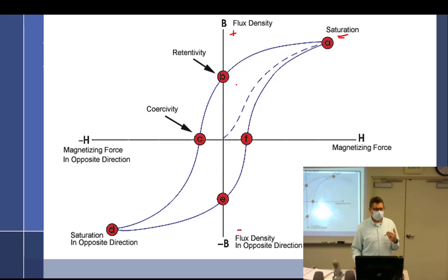And again, it's kind of cool because a lot of you have already done this. I'm trying to remember those that haven't. When you're putting the fluid on a part, there's two methods of doing it. One is called continuous flow, and the other one's residual. So in a continuous flow inspection, I take that fluid, so there's a fluid bath with these iron filings in there, and I will actually get the part very, very wet.